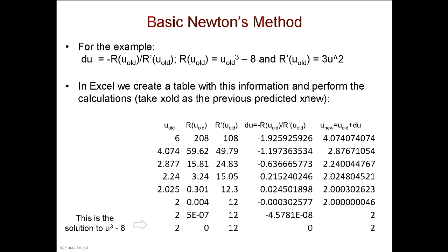Now, I don't know if you've noticed, have you run Abaqus and looked at the message file? You should open the message file, and you will see that Abaqus, for the buckling problem particularly, is actually iterating to try to get to the final answer. It's applying the Newton-Raphson procedure, Newton's method, this is called Newton's method, by the way, to solve this equation. Now, this is a single equation, right?